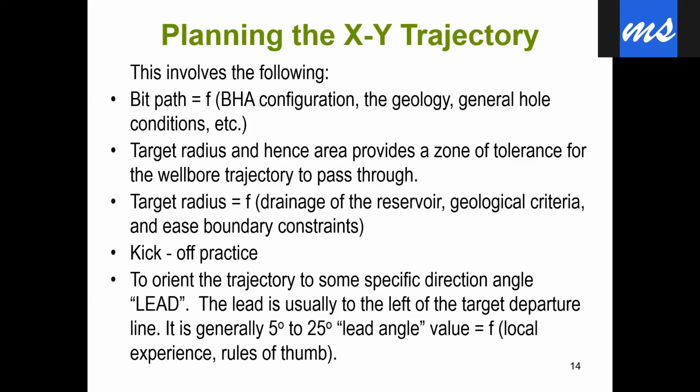Thus, any well drilled in consolidated formation, the path will go to the right, because we are turning the drilling string to the right, so it creates a walking effect on the bit. So normally the bit walks to the right, and it will be a big issue because normally we need to correct the azimuth.